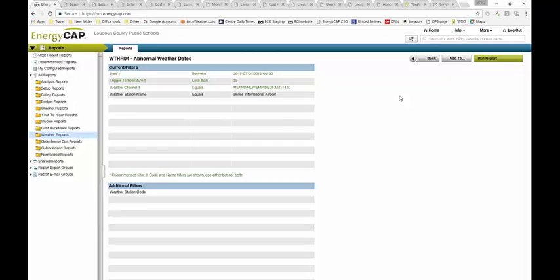If you were concerned about sprinkler pipes freezing, so that when you get below a certain temperature in certain buildings, maybe older buildings that aren't insulated as well, you go into freeze protection mode and crank up the heat all night long, because using some extra energy is better than having a burst pipe.